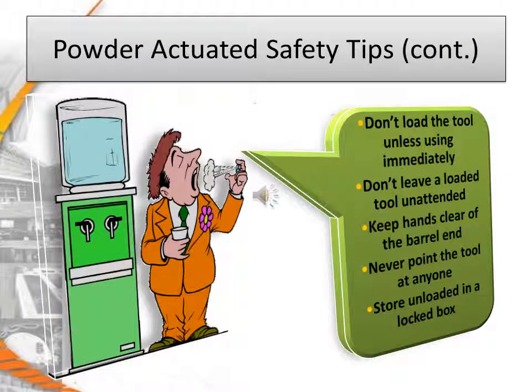Don't load the tool unless you're using it immediately. Don't leave a loaded tool unattended. Keep hands clear of the barrel and never point the tool at anyone, and store it unloaded in a locked box.